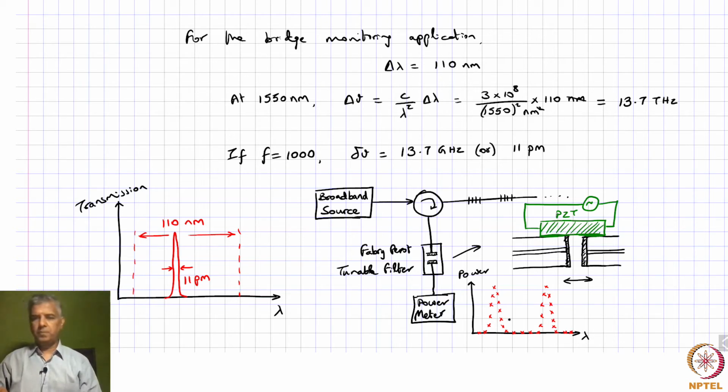So clearly, if one of these gratings is measured, from that spectrum you can figure out what lambda b1, lambda b2 and so on are. Based on some perturbation, this lambda is going to change, and if you pick up the corresponding Bragg wavelength change, you can figure out how much your perturbation is.